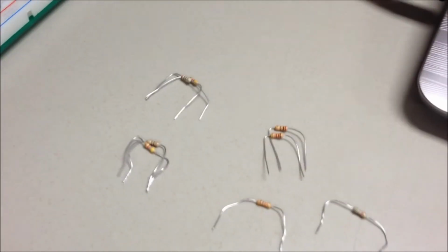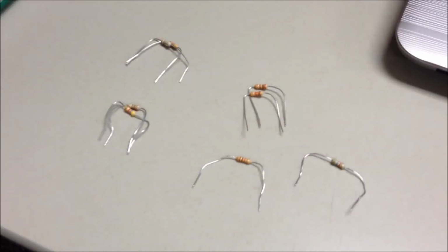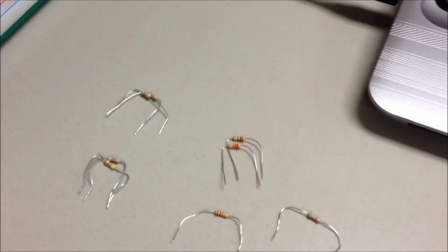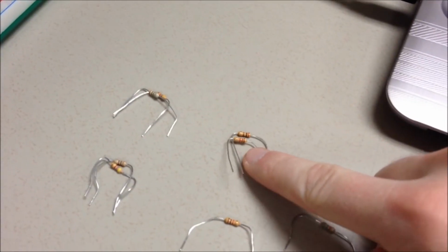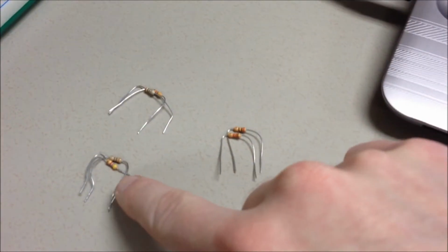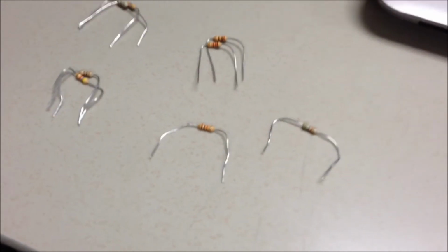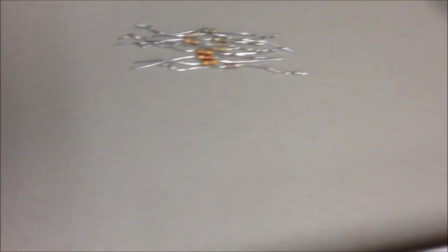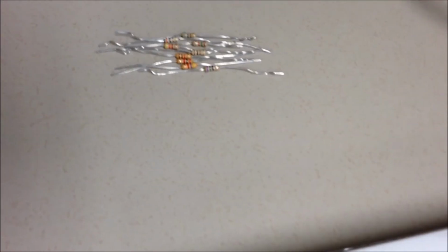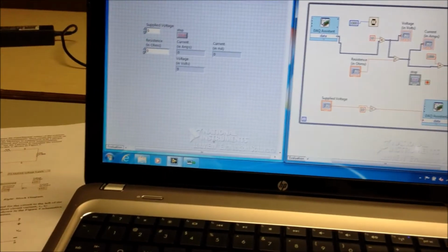Now if you don't have all these resistance values available to you, you can use resistors put in series, like I've done here. You'll see that later in the circuit, just to find the values that are listed in the laboratory. Also, you're going to need 10 resistors to use as load testing values, so make sure to get those, and then you're pretty much ready to go.